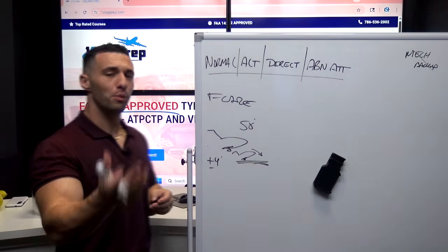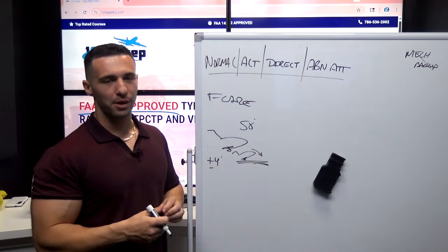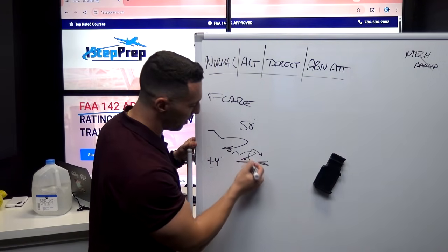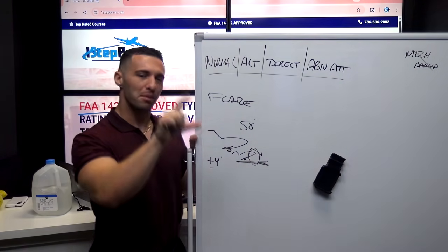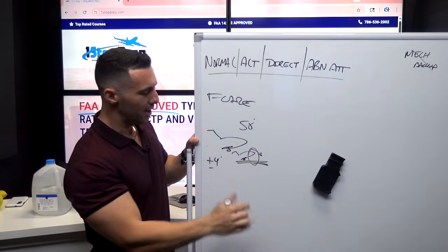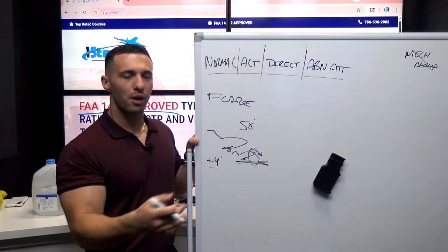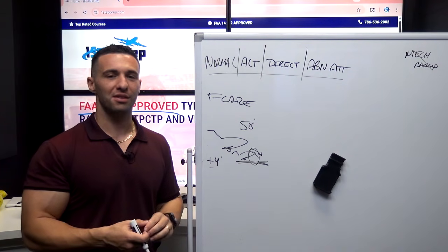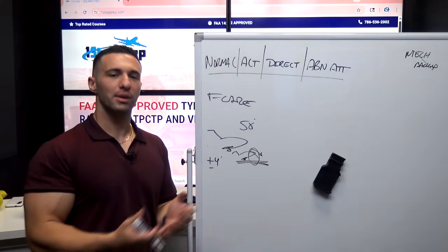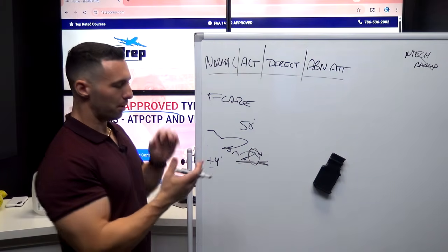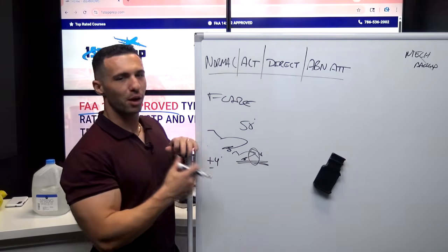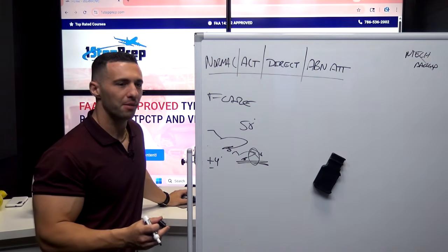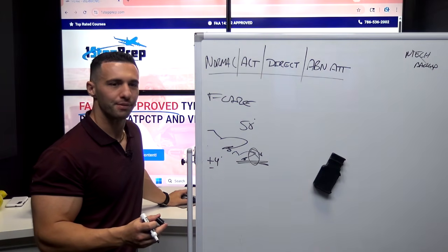And so the only reason we have to continually add this aft elevator input is because the flare mode is effectively taking the nose, and I like to think of it as almost a rubber band that's just compressing the nose down towards the runway. And as it brings the nose down, I have no other option but to continually apply my aft elevator inputs, which is natural to the sensation I would have if I were landing any other airplane. So that's one of the dominant reasons why we have that flare mode in normal law. Hopefully this makes sense. And with that, that effectively covers the 3 different modes that we have.